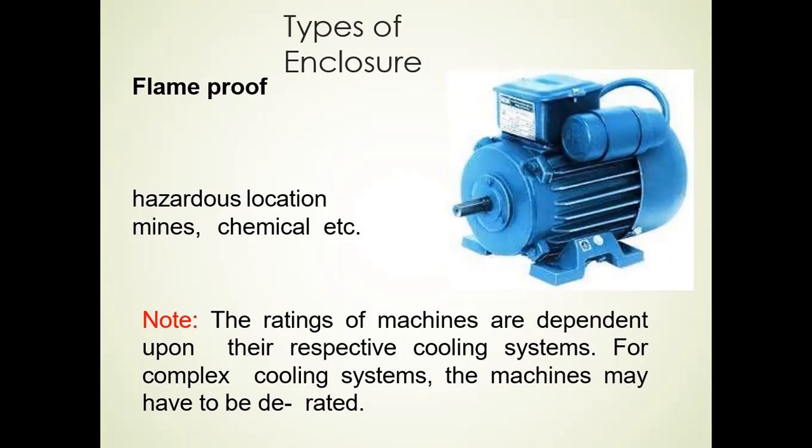What are the scope of standard recommendations for degree of protection? That is one of the important question for this coolant as well as our enclosure system. It is like a protection, right? So standard degrees of protection by enclosures applicable to electrical rotating machines as regards the protection of persons against contact with live or moving parts inside the enclosure and protection of machines against ingress of solid foreign bodies.